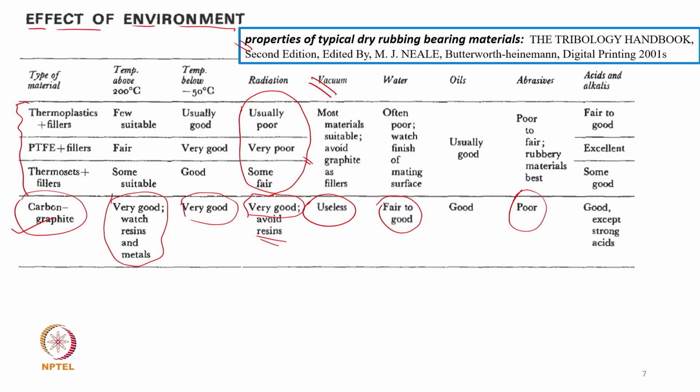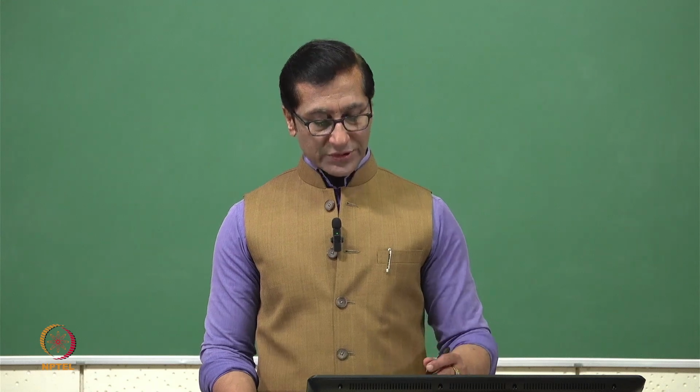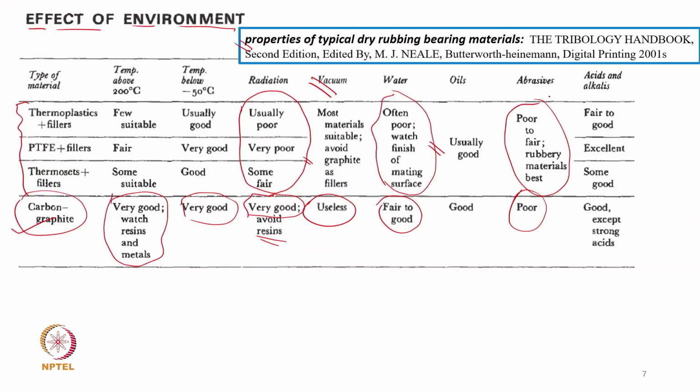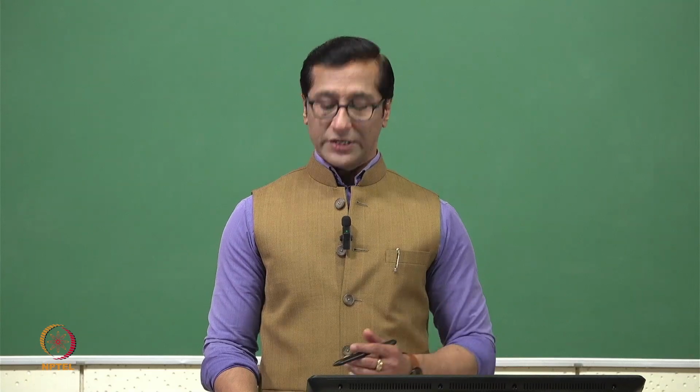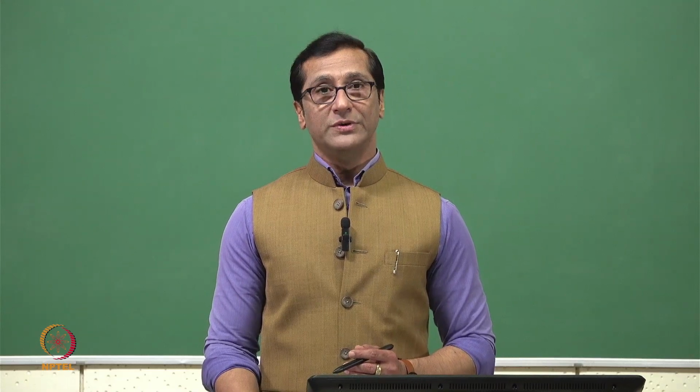Another one, in the presence of water, carbon graphite is giving very good results, but in the presence of water, polymer will not give good results. So this is very important. Of course, in the abrasive case, again they don't have good properties to resist the abrasion. Actually, it will not really show good performance.